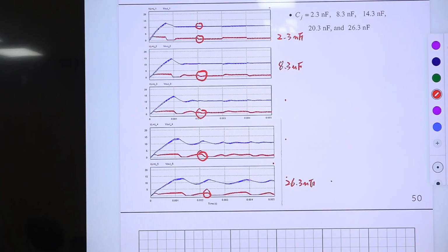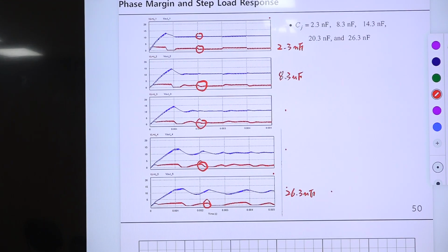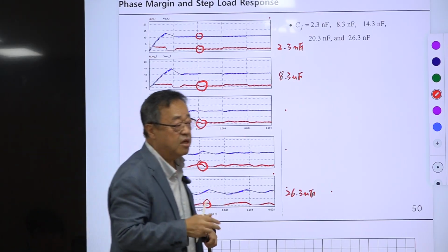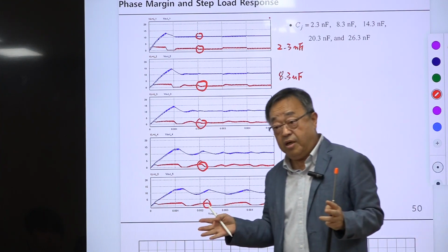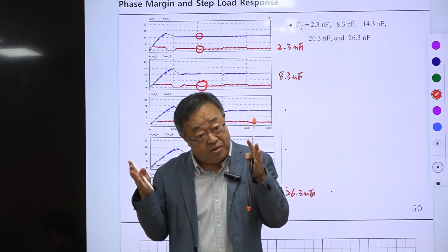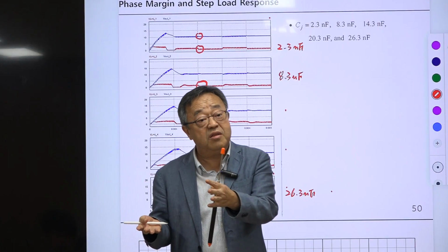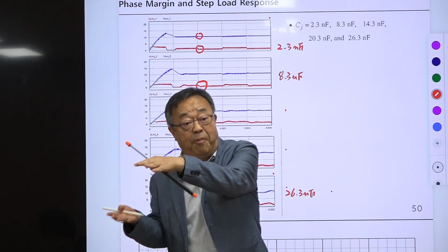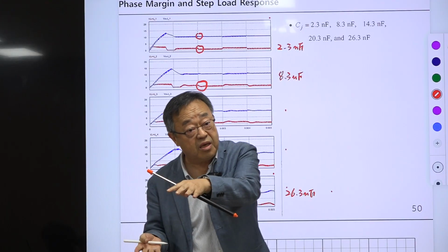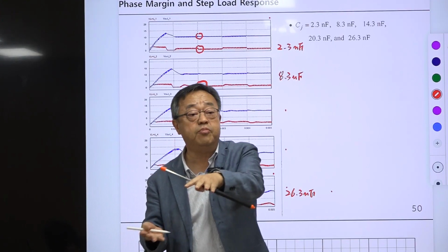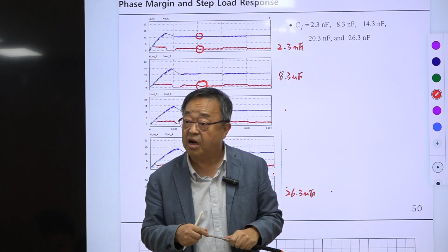A similar situation will occur, okay, this is the end of this lecture. It's something else. You have a power supply. Then you may add a capacitor in parallel with your output capacitor to improve something. That disturbs the location of the ESR zero.